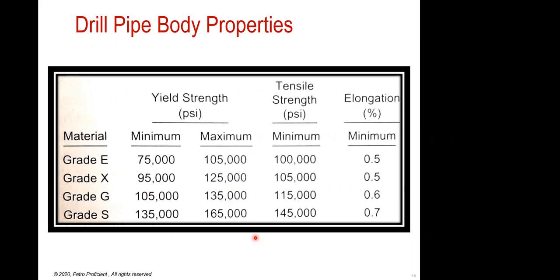In other words, as you go deeper and you have longer pipe sections, the drill pipe needs to be of higher grade. And in directional wells, as we will talk, drill pipes are subjected to a variety of loads other than just vertical, axial loads. They also have torsional loads, they have torque and drag. There are so many different loads that need to be accounted for, and thus the pipe has to be stronger.